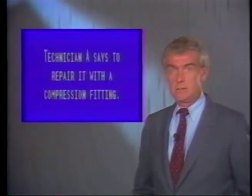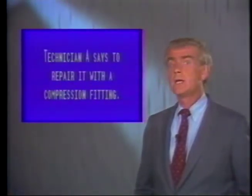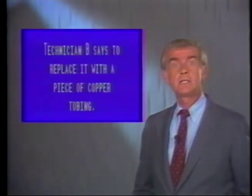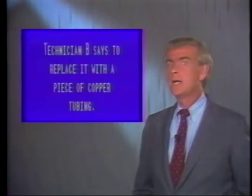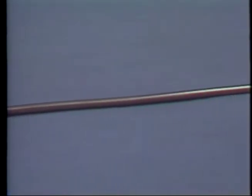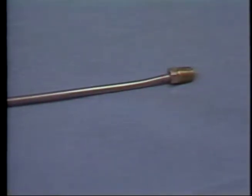Technician A's statement is false. Brake lines should always be replaced if they're damaged. Technician B's statement is also false. Brake lines should never be replaced with copper tubing. Most brake lines are double-walled steel that are coated to resist rust and corrosion. The correct answer is response D, neither A nor B.